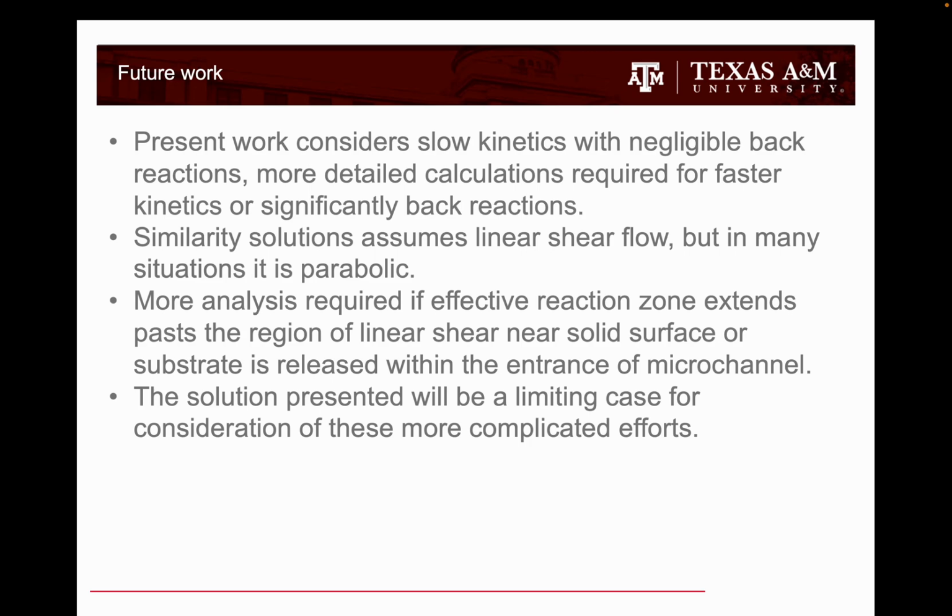Likewise, the similarity solutions which we have assumed here assume linear flow, which means that as we move away from the surface, the effect of the no slip condition varies. The no slip condition mitigates as we move towards the center, and this varies linearly with the position. But there are situations where it varies parabolically, so we need to consider that also.